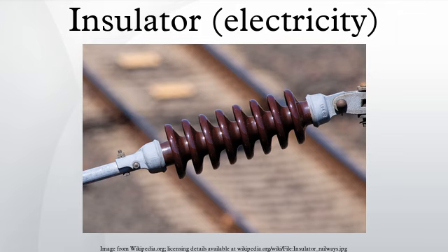In very high voltage lines the insulator may be surrounded by corona rings. These typically consist of toruses of aluminium or copper tubing attached to the line. They are designed to reduce the electric field at the point where the insulator is attached to the line, to prevent corona discharge, which results in power losses.